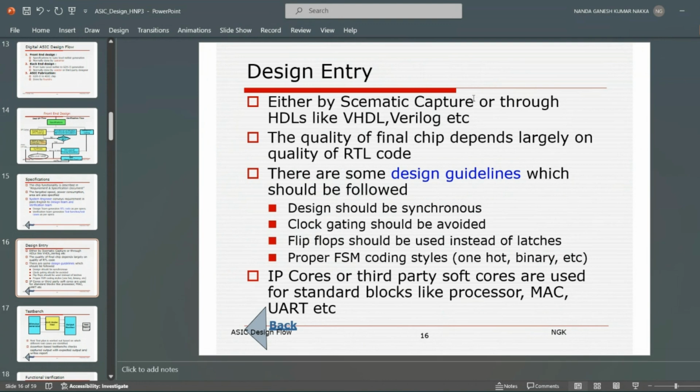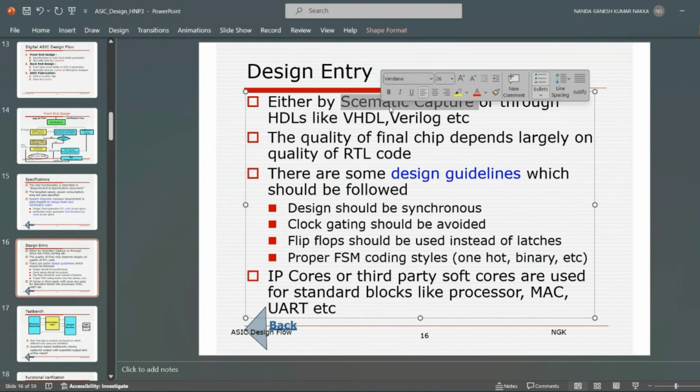As I said, the first design methodology. If you already have a previous version and we are just replicating it, then we directly take the previous version which is already taped in and came to the customer in the outside market. We take that schematic capture and we update on that. Let's say Qualcomm Snapdragon has already released one version, 810, and they're going to release 811, which is almost similar with few changes.